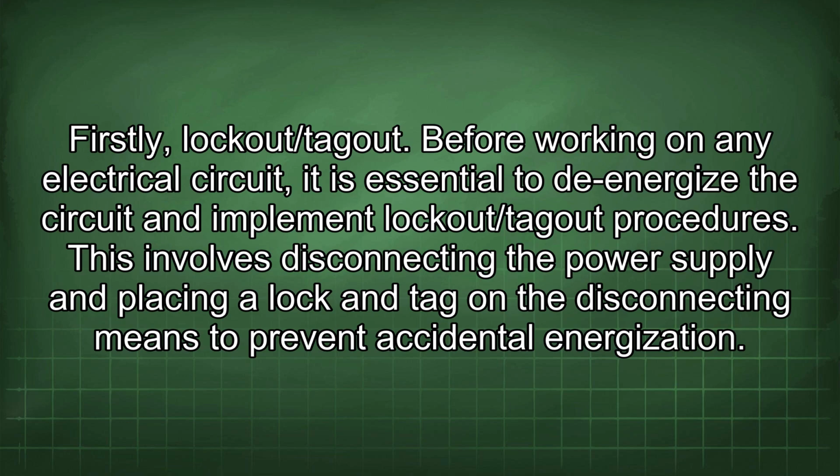Firstly, lockout/tagout. Before working on any electrical circuit, it is essential to de-energize the circuit and implement lockout/tagout procedures. This involves disconnecting the power supply and placing a lock and tag on the disconnecting means to prevent accidental energization.